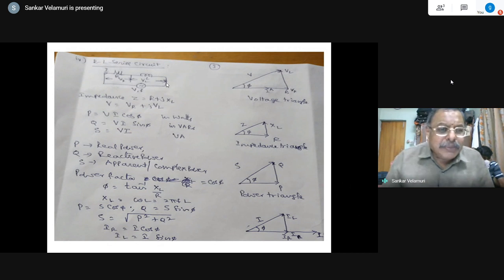The current has two components, the real part and the reactive part, which can also be understood here. The total applied voltage is V equal to VR plus jVL, where f is the frequency. Here you can see the voltage triangle. I is taken as the reference phasor. VR is I into R, not to the magnitude drawn here, but it is a representation. And VL is leading by 90 degrees with respect to the current. I observed a slight deviation in the drawing, but it is taken as a perpendicular line.